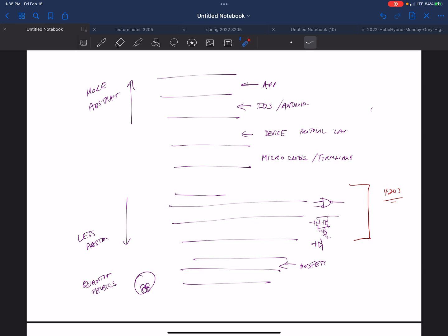called logic families. At the moment, really there is no other logic family other than CMOS, honestly. I can't think of anything else. There used to be lots of, if you work in the space program or some military stuff where they're using old stuff because everything has a 20-year lifetime, you might have heard of TTL or some other weird logic families that no longer exist. There was a while where they had different logic families that you could choose from, and they would have different characteristics, but now, essentially, you have one logic family. It's called CMOS, static logic family.